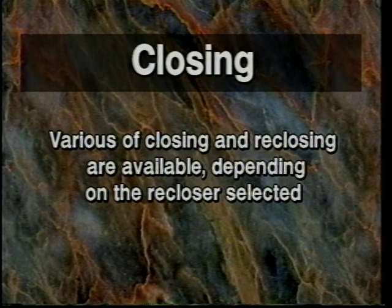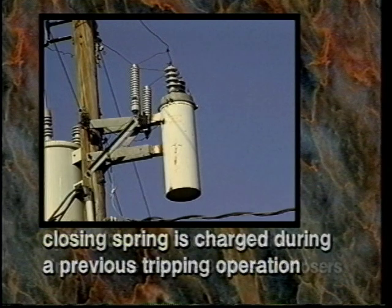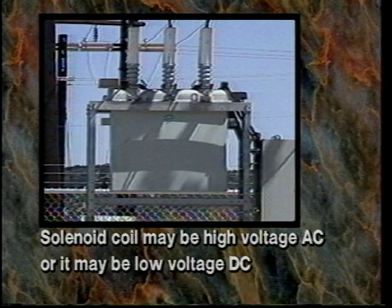Closing. Various methods of closing and reclosing are available, depending on the recloser selected. Spring closing is utilized on most single-phase reclosers and some three-phase reclosers. In each case, the closing spring is charged during a previous tripping operation. Solenoid closing is utilized on some single-phase reclosers and some three-phase reclosers. The solenoid coil may be high-voltage AC or it may be low-voltage DC.